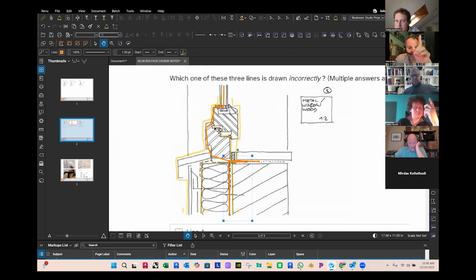Insulation line is the same. If you do it within an isothermic calculation, you would see the lines being narrowed down to the insulation glass, and then it spreads out because wood, for instance, would distribute the warmth or the temperatures in the bigger element. Aluminium can be a little bit tricky where the line goes, depending on the layers of the thermal barriers.